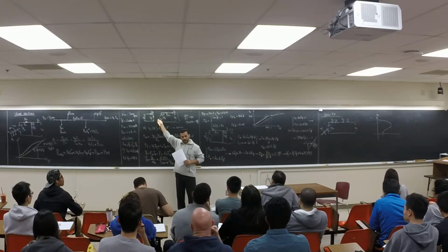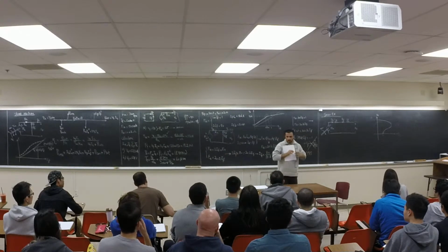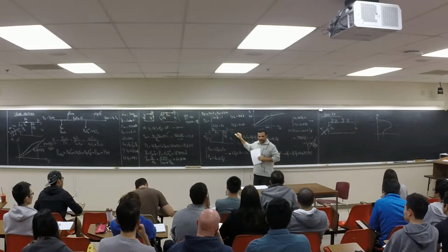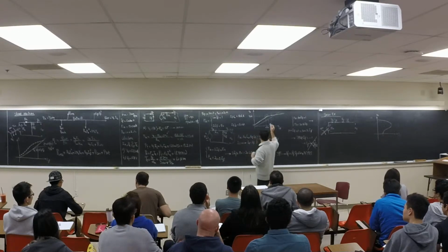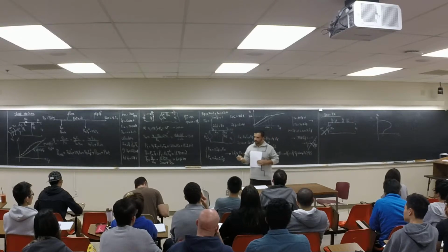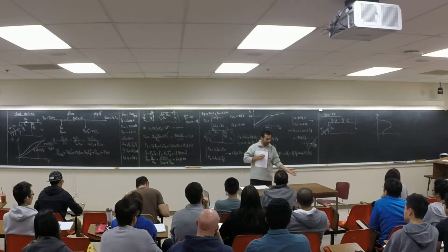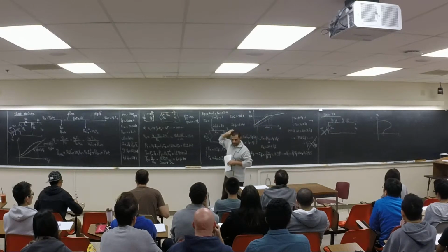Because this is a source, right? There is no limitation here. But over there is a limitation. Why? Because when you short here, think about it. The current here is going to reduce, right? So automatically, it's going to bring the voltage down in this curve, right? How can you protect against short circuit? If you can bring your voltage down, the short circuit is going to go away, right? So automatically it adjusts, and somewhere it's going to give you some current. It's not unlimited current to fuel your machine, right?